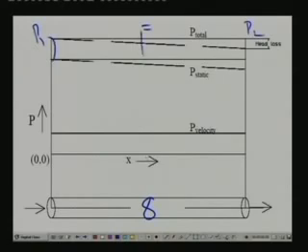What happens when you are putting a pump? When you are keeping a pump or a fan in the pipe flow, the velocity pressure does not change, because the fan or pump does not increase the mass flow rate. So, velocity pressure remains same, but it increases the static pressure because it adds energy to the fluid. So, at the point where you have added the pump, the static pressure increases. Okay. So, you have the modified pressure lines with the addition of pump or fan inside the fluid circuit.